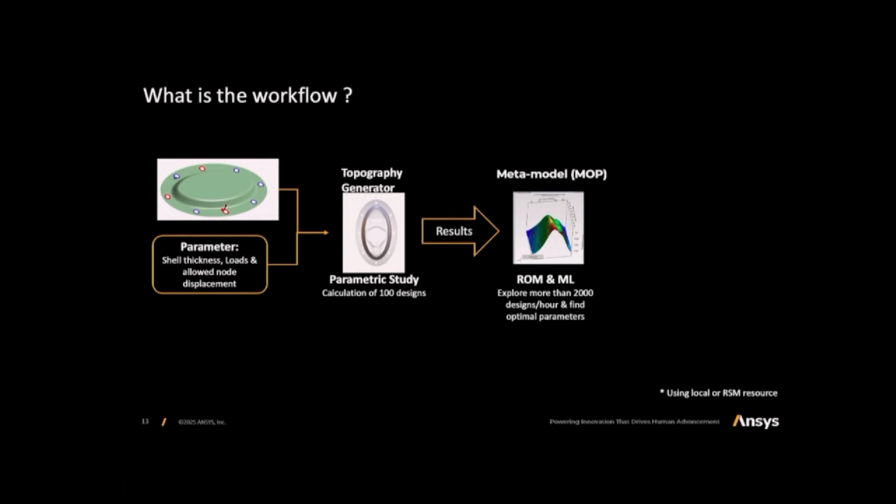So the next example that I'm going to talk about is looking at acoustics, which we heard about in acoustics analysis. And again, with sheet metal analysis, I'll go through some of this fairly quickly, but this is an example of being able to take a sheet metal part and doing a topography optimization, basing that topography optimization off of the acoustic performance and the stiffness of this sheet metal stamped part. So we can go through that.